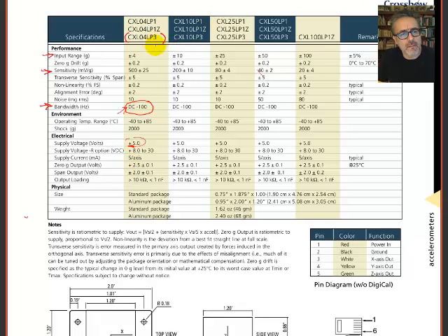That's what the 3 means here. It is a 3-axis accelerometer. So if you had accelerometers sitting in space and there was no acceleration in all 3 axes, you'd see ideally 2.5 volts out of each channel, right? There's going to be 3 channels for these 3-axis accelerometers.